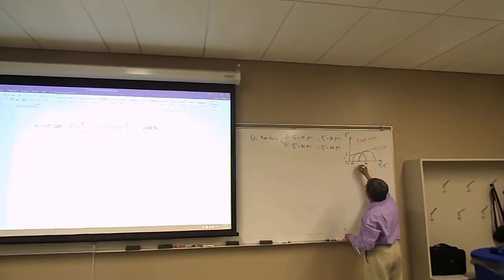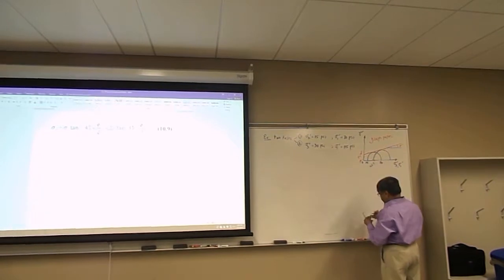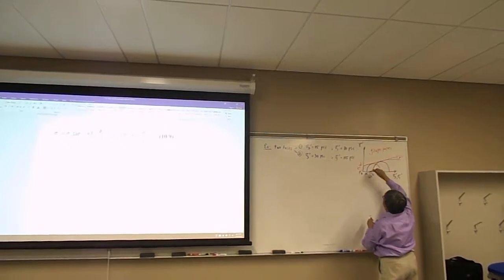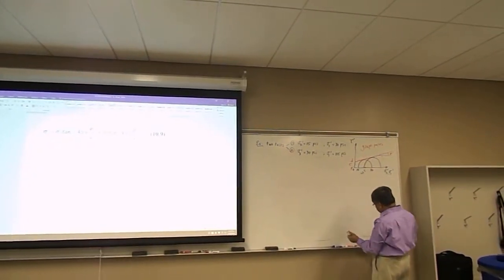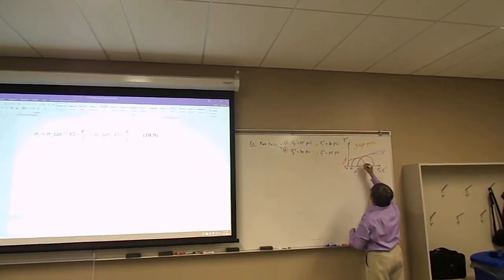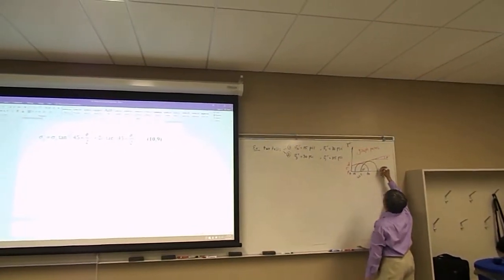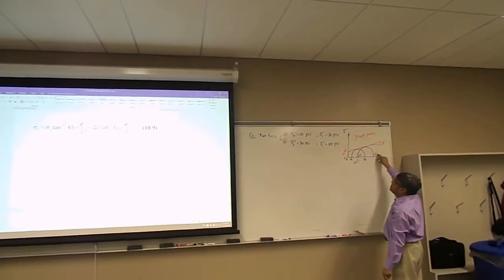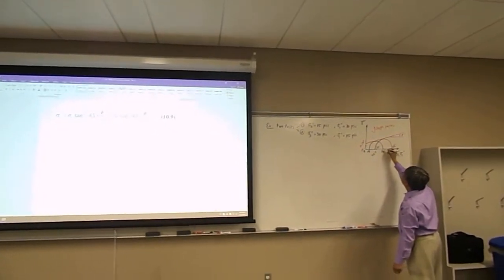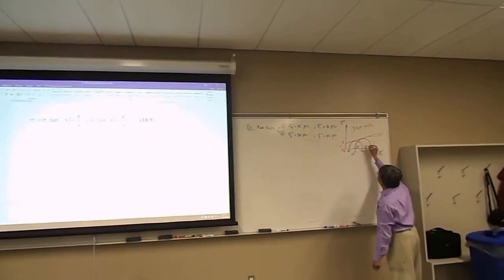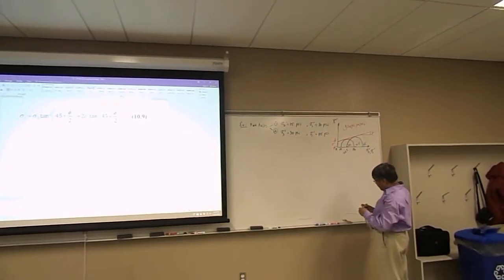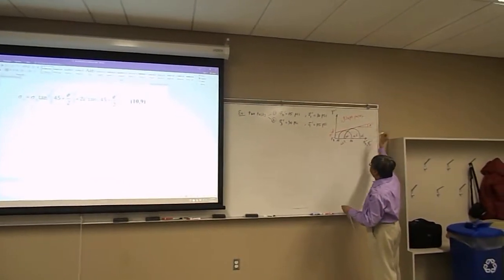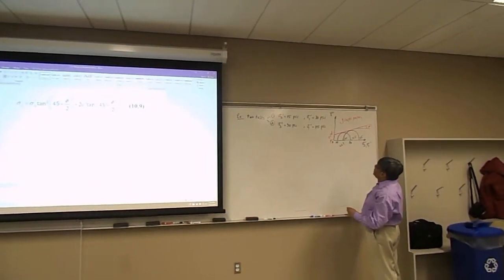Once you put the center at 42.5, you take the compass to draw this circle. And for these two, this being 30, this being 115, this is 145 the total, so half of it is 72.5. From 72.5 you need to draw this circle, and you need a straight edge to draw the common tangent, and you can get that.